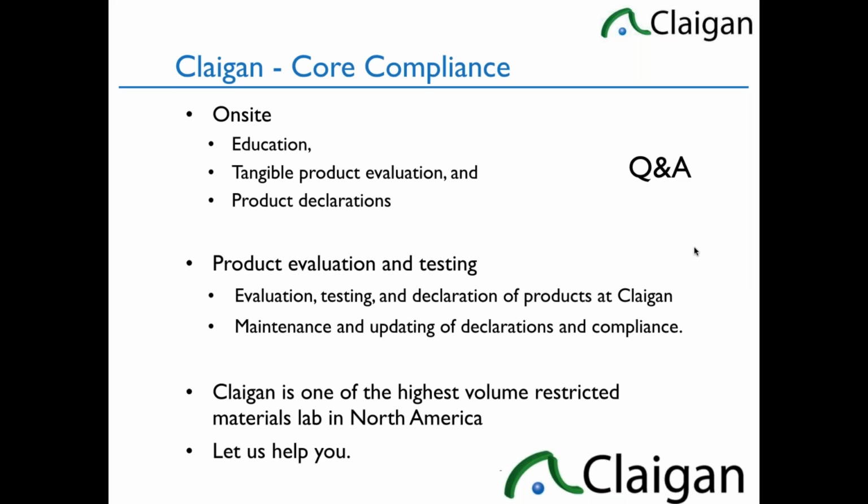So back to UAE: is there any testing requirement? It's not clear. It looks like it can be a technical file because they mentioned EN 50581. We're talking about UAE RoHS, not Taiwan, Taiwan's different. Whether there's a testing requirement, there's likely a registration requirement. It's more obvious for some. If you submit an RoHS test report, that easily meets it, as you can see from the preliminary material. But because they mentioned EN 50581, a technical file would likely also be sufficient, but it's not clear at this point in time.